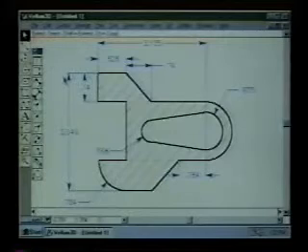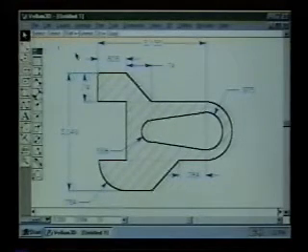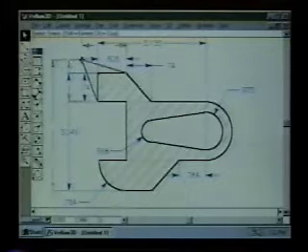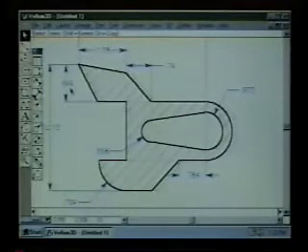Now one other thing to show you, notice that this dimension is 828 and this dimension is 0.74. If I select this corner and drag it up, see how it changes, and notice the values 964 and 138. So what we see here is associative hatching and associative dimensions.